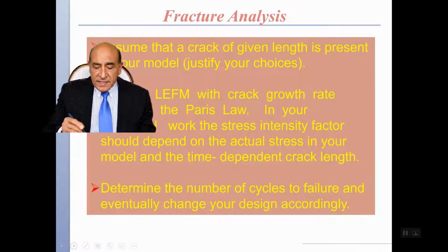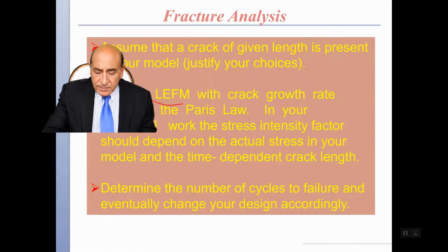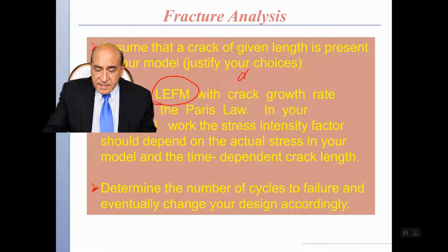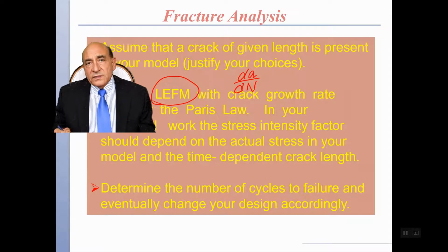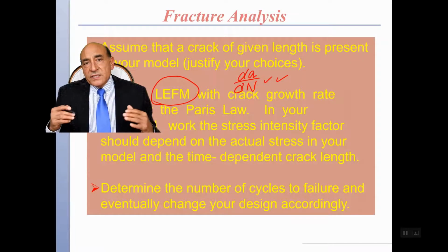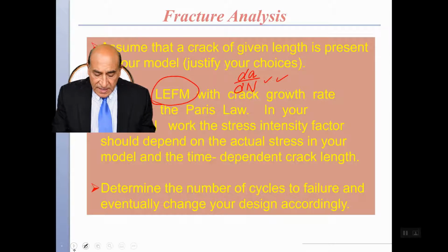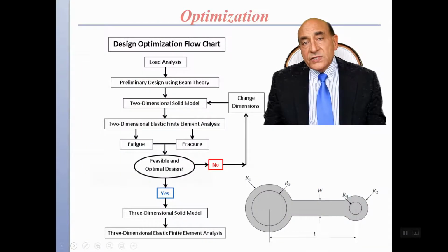This initial crack size is going to be described by linear elastic fracture mechanics, LEFM, using an equation that is based on the Paris law, the very well-known Paris law, in which the crack growth is dA by dN, the rate of change of the size A with respect to every cycle. We have a function that we will introduce, and this function will be integrated to grow the crack until we get failure. So having done that, it gives us really the ingredients to do an optimization.